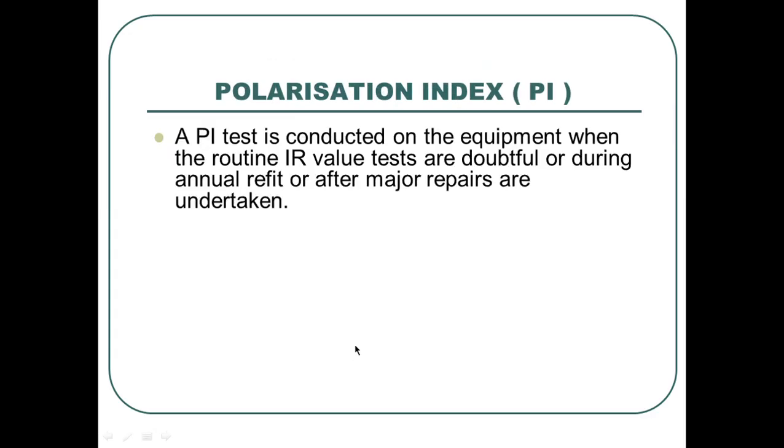Now, what is polarization index? A PI test is conducted on the equipment when the routine IR value tests are doubtful, or during annual refit, or after major repair is undertaken. When we are not satisfied with the IR test, then we do this PI.